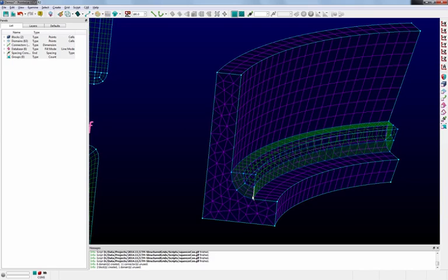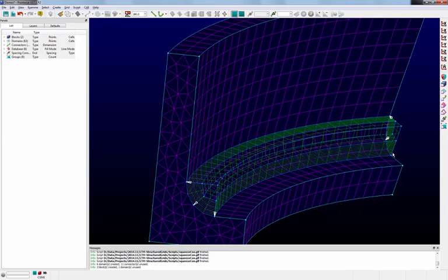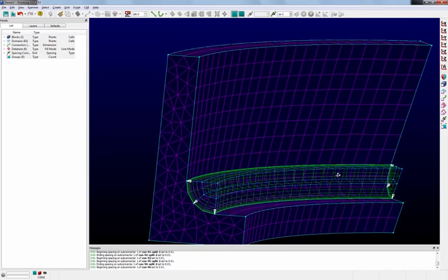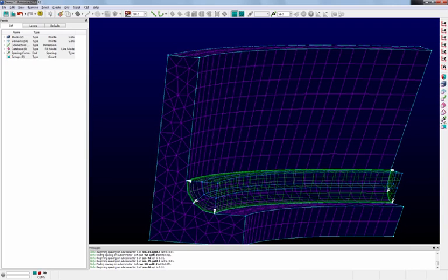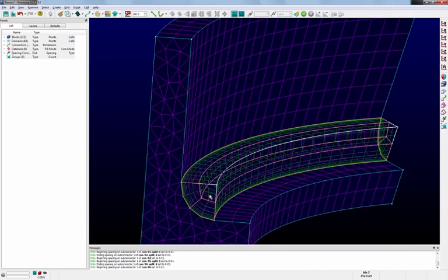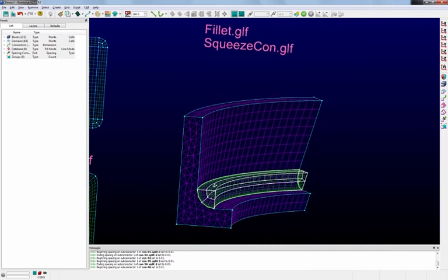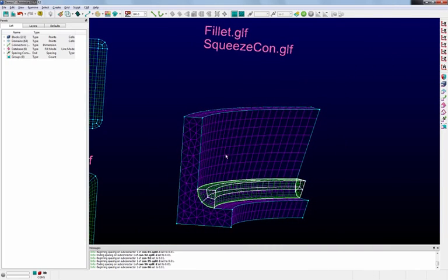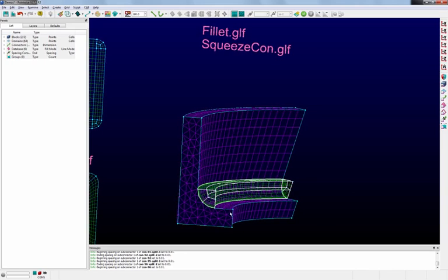We can then go through and highlight these 6 spacing constraints here so that we get a nice tight spacing there near the wall, and I'll just type in 1e to the minus 2 there for that spacing. And so you can see that we now have a very good quality boundary layer resolved block, and moreover we've now presented 2 orthogonal faces that can be used to construct the blocks coming off of the blade and the hub.